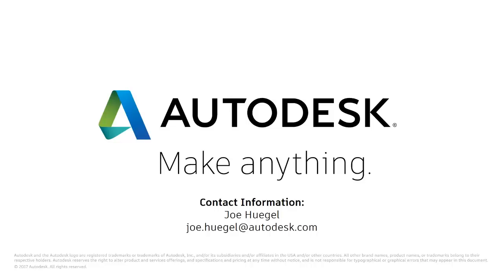Okay, gotcha. Next one, how does the software represent mold components? Do you have to model them in Moldflow? Yeah, so specifically to answer that question, there's a handful of ways that Moldflow can use different geometry. So whether you're using a design from part only and you want to build your mold inserts in Moldflow, we have the ability to do that.